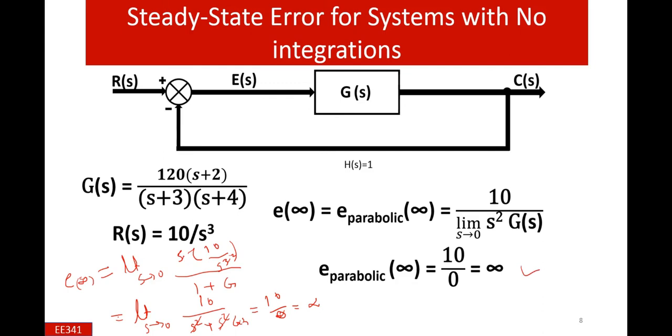It means if we find the steady state error for the same system with step input, the error is constant, but if we change the type of the input to the ramp input, the same system gives an infinite steady state error, and similarly for the parabolic input.